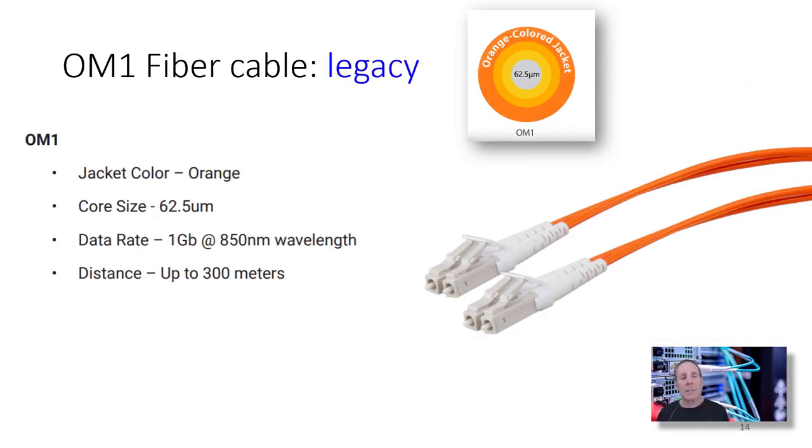It has an orange jacket. The core size is 62.5 micrometers. It has a data rate of about 1 gigabit per second, and it uses the 850 nanometer wavelength. It can go about 300 meters.